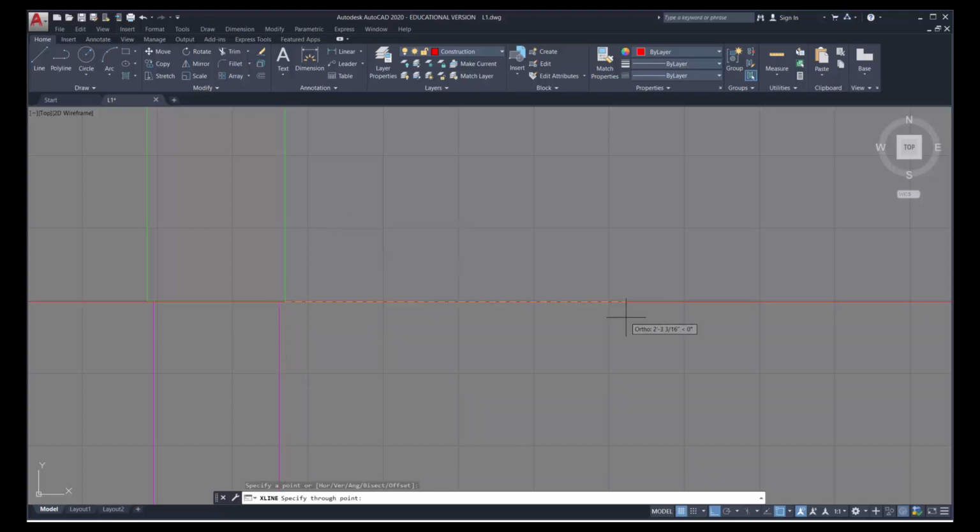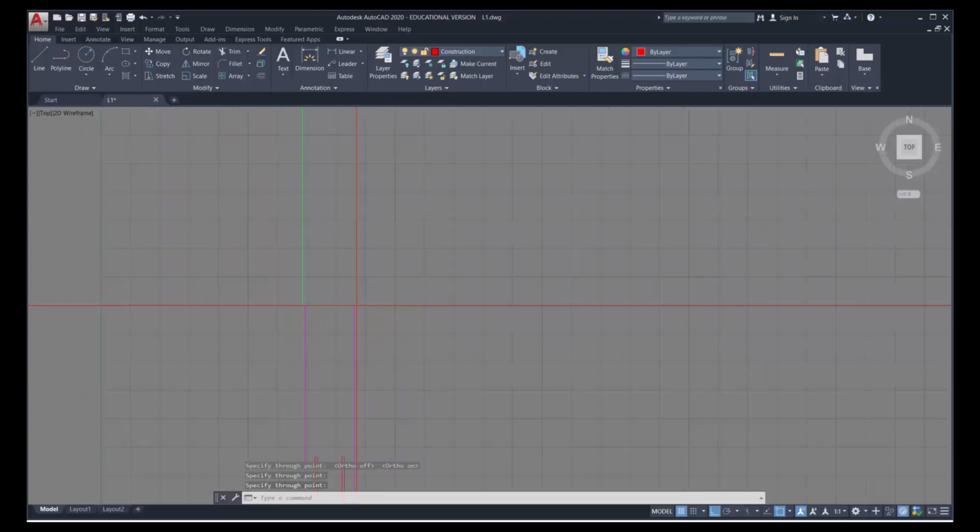It's the snap position. Now you'll notice mine is already going straight up and down. My F8 key was on or toggled. If I press it again, I can rotate that line. For what we want to do, we want to put the F8 key on. And the sequence is simply move your mouse up, click once, move your mouse down until you get a horizontal line, click again, and press enter. That's all we need to do.